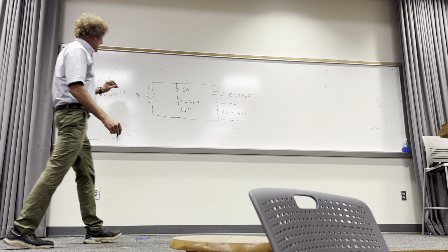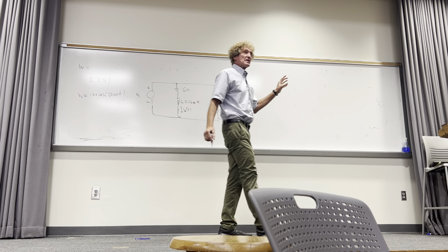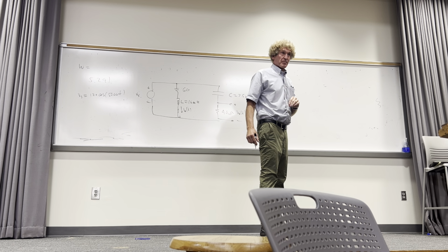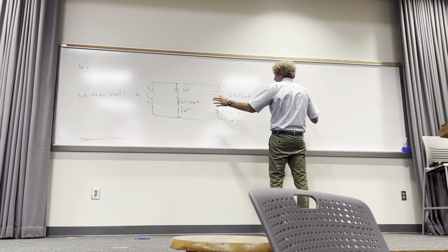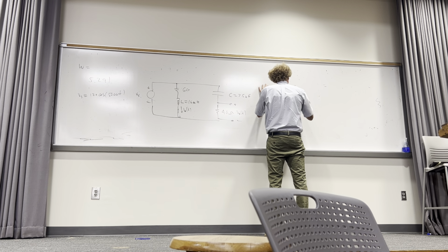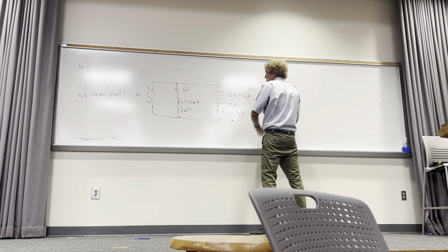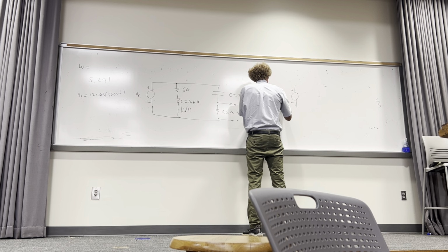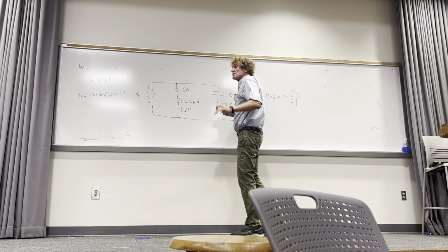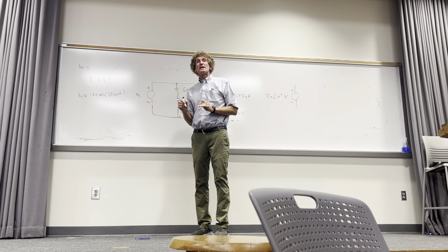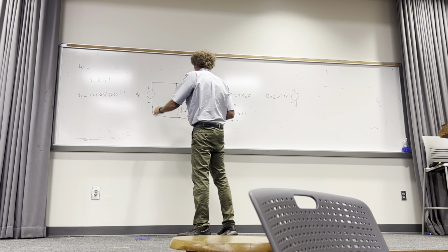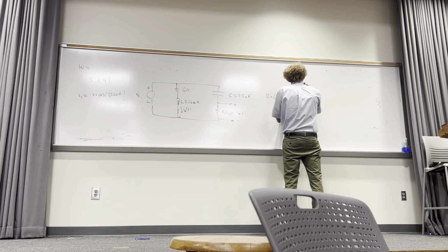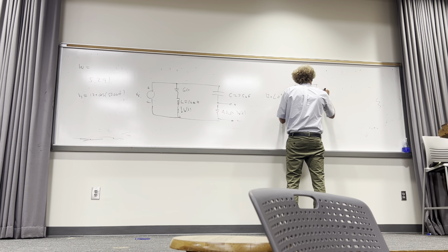So now I'm going to take this and put it in the phasor domain. Everybody with me? We'll get all the quantities. So over here, we'll take it back to the time domain. I've got a voltage here, plus to minus. The magnitude is 120. The angle is 0 degrees, and the units are volts. We're in the phasor domain. Everybody with me on that? Next thing we're going to do is take that 60 ohms. It's 60 ohms every which way. So it's 60 ohms here.